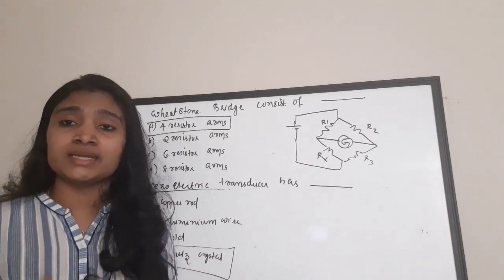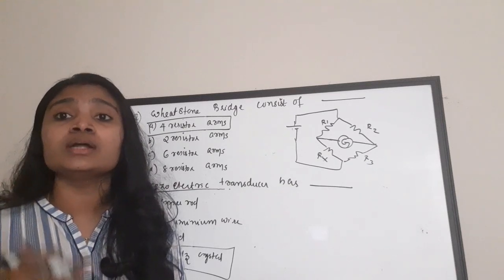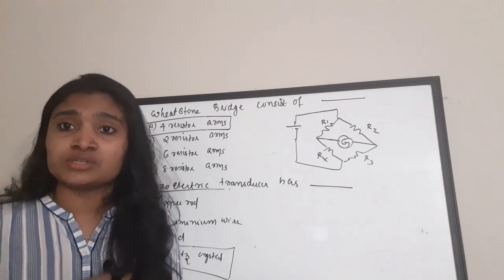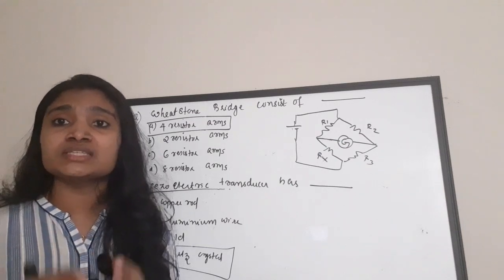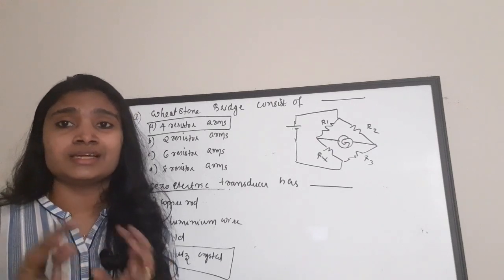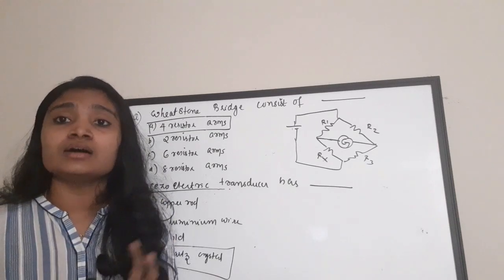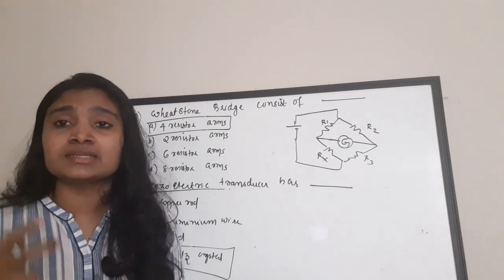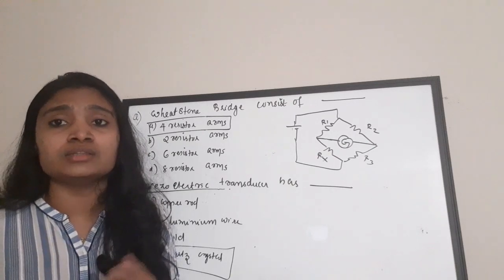Now, what is the piezoelectric transducer? This piezoelectric transducer is used to find non-electric quantities such as stress, strain, acceleration, vibration, etc. So these quantities are measured using a piezoelectric transducer. If these quantities are applied, due to some stress, it will generate some voltage. That is the quality of a piezoelectric material. Also, these piezoelectric materials can produce high voltage with low current. It is another feature of the piezoelectric transducer.